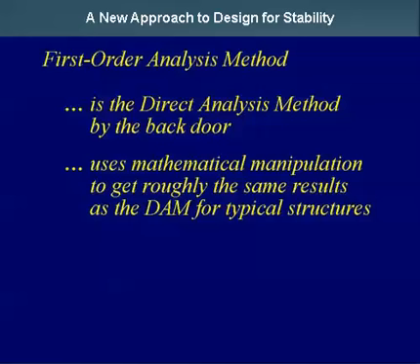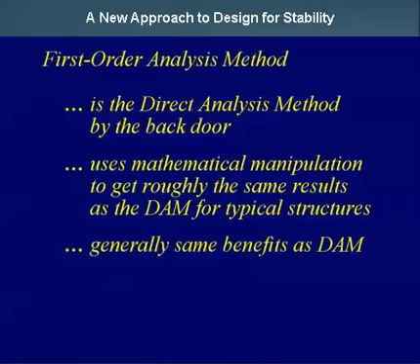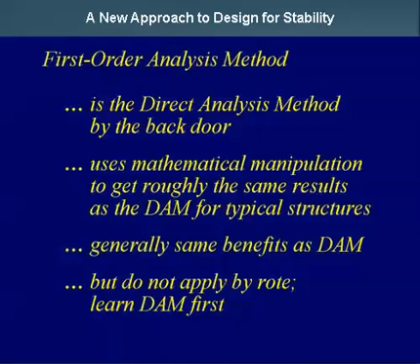It is the direct analysis method by the back door. It just uses mathematical manipulation, so there's no real independent logic to it. Generally it has the same benefits as the direct analysis method. So it is a powerful method, but I must advise everyone not to apply this by rote.